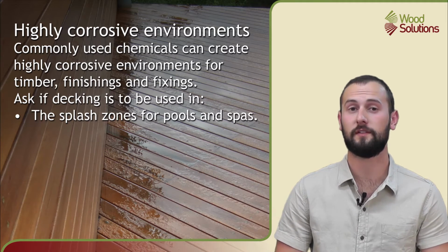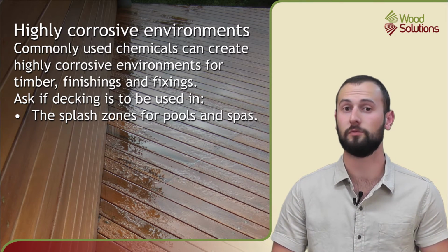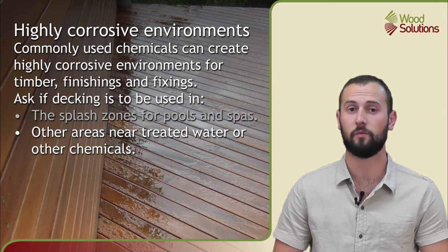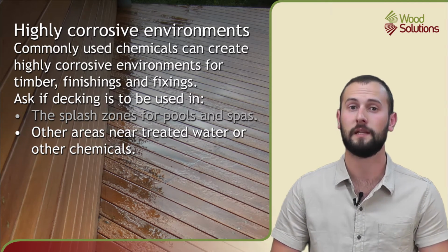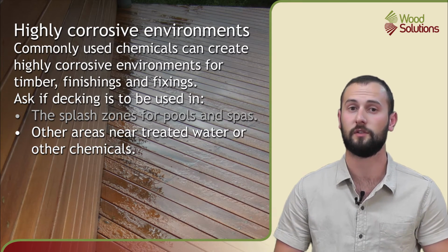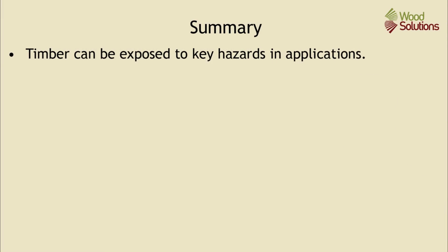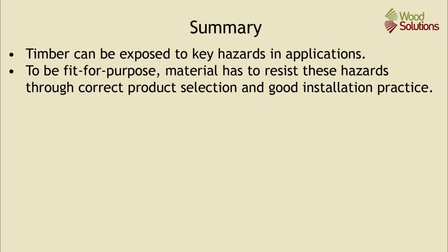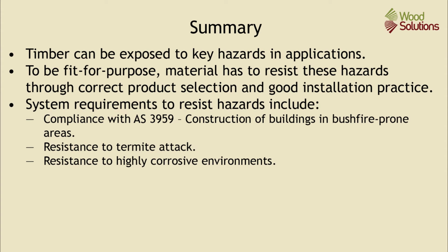Ask if decking or other timber is to be used in the splash zones for pools and spas, or in other areas near treated water or similar chemicals, and recommend to the customer that they get specialist advice on fixings and coatings. In summary, timber can be exposed to key hazards in applications. To be fit for purpose, material has to resist these hazards through correct product selection and good installation practice. The requirements of the products and systems to resist these hazards include compliance with AS 3959, construction of buildings in bushfire-prone areas, resistance to termite attack, and resistance to highly corrosive environments.